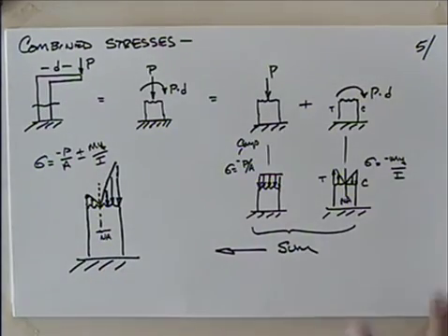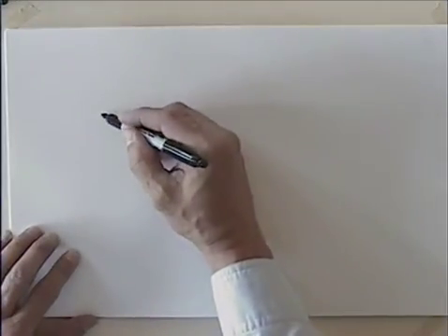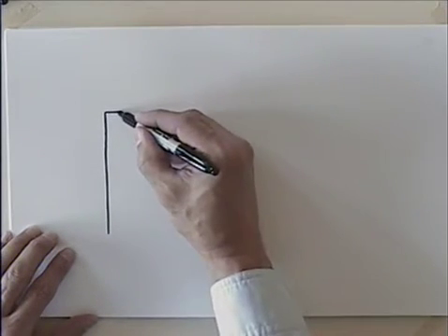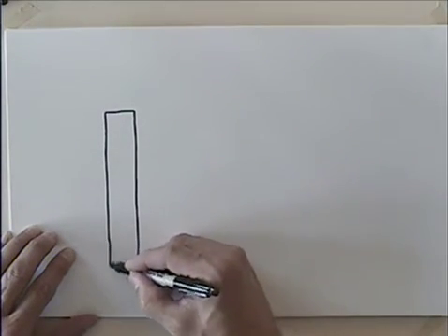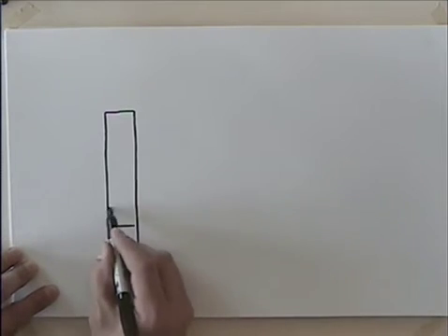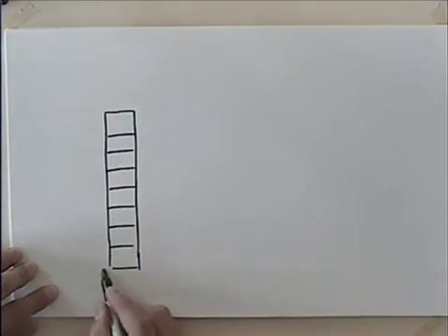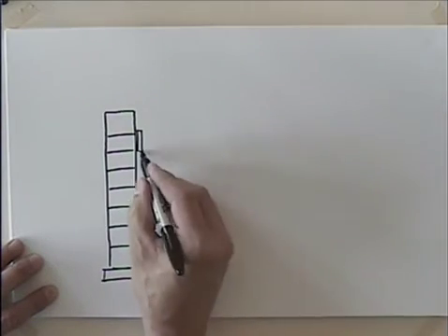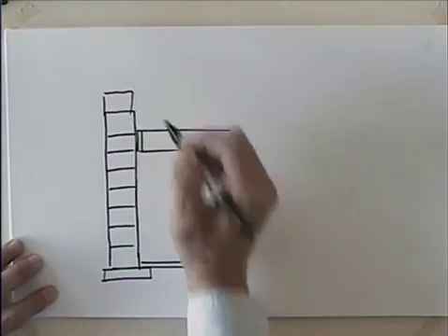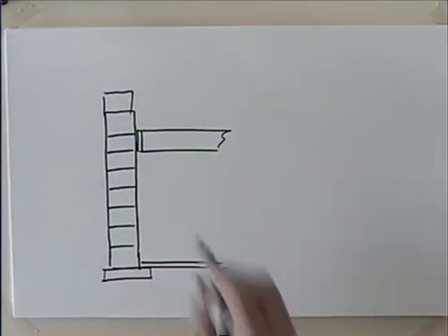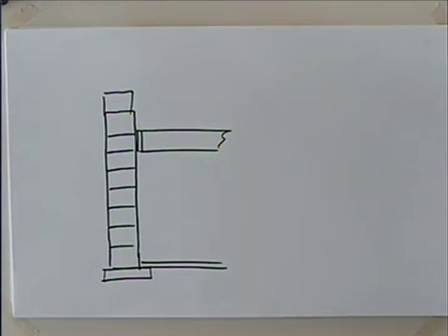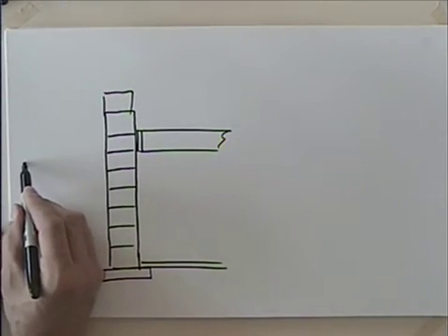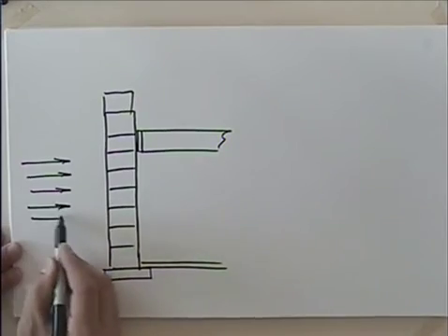And this is something that comes up quite a bit. Let me look at an example. You go downtown in really any town, certainly downtown Salem, and you look at the way buildings might be constructed. They might have some concrete block buildings. We call them CMU, concrete masonry units. So we've got these blocks that are stacked up. This is on a foundation here. Then someone has come in and poured a floor, and maybe they put a ledger on this. They've got the roof structure in here, and maybe they've got a parapet. They tend to put those parapets on for fire safety. So they either have a floor and a roof, a very, very common arrangement. And let's say that we have some load on this from this direction. This could either be wind or seismic.